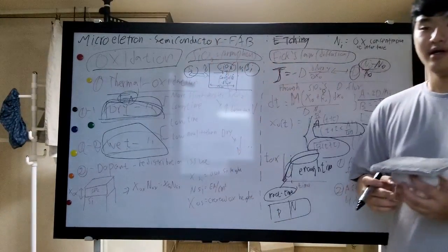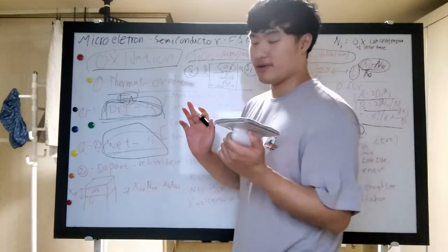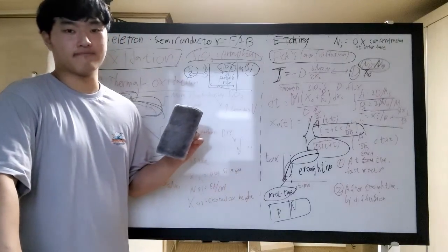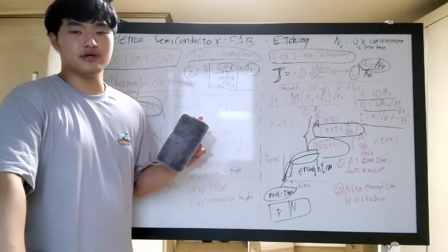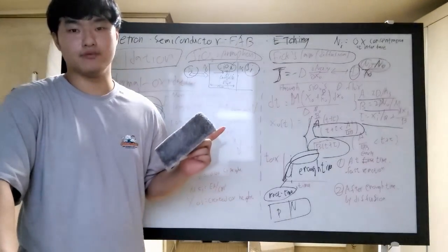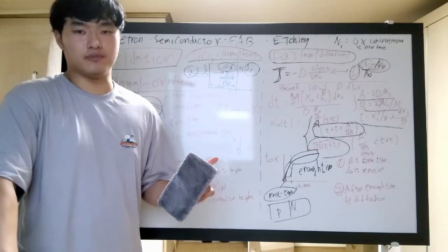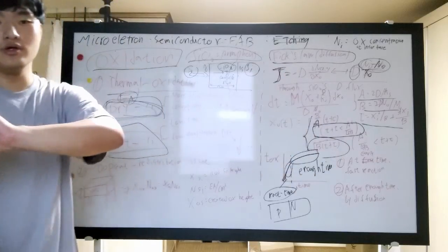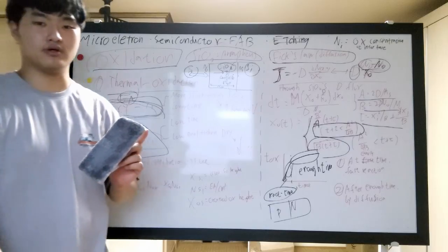And for another respect, let's see, we just made some enough thickness of dioxide. Then here's one problem. During the oxidation process, how will the dopant be redistributed in each region? Where will the dopant be moved, to the dioxide or to the original side they belong to, like the silicon or doped silicon?